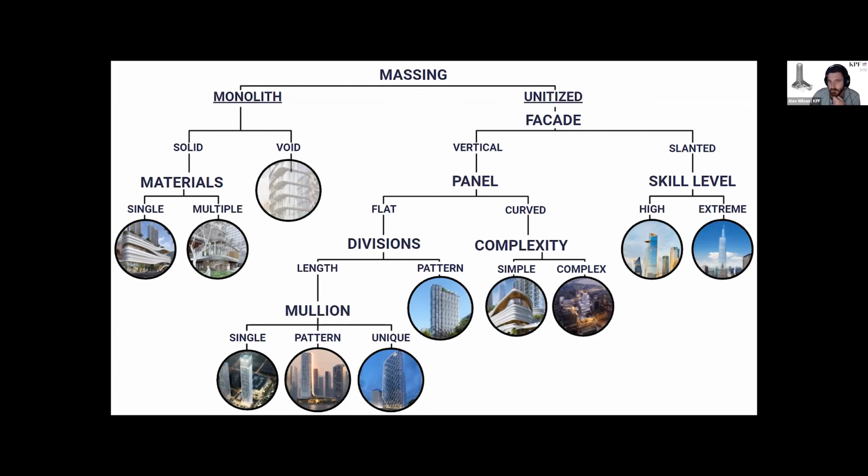For example, the Wuhan project, which you can see on the far left here, that organic curved sweeping facade. We were looking at a solution for using Rhino to document the profiles at each of the panels. So basically slicing it up using Grasshopper, getting those profiles, placing that on sheets, to help the team accurately describe the construction method used for these panels, and then them being sent off. We've actually had some tests for that constructed at the moment.